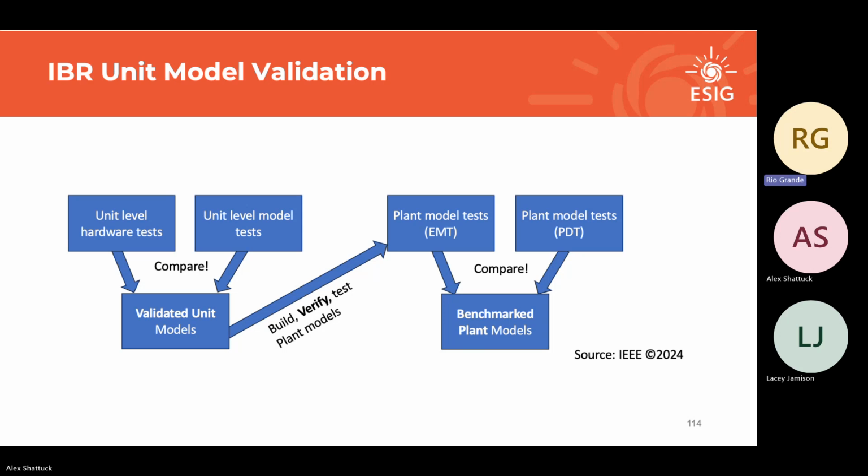I like to do them both at the same time. You will be doing both at the same time in the design evaluation, so you're not missing it. But there's a lot of concern about setting up that test, and a lot of concern about the extra value it brought, right? And my take is the value is that you catch those handoff issues. Because there's certain things that a plant controller can do to just get out of the way of the inverters during the fault. And really studying the handoff and how it comes back into plant controller control, and the windups and any sort of weird behaviors, is, I think, really important. But I lost that argument, right?